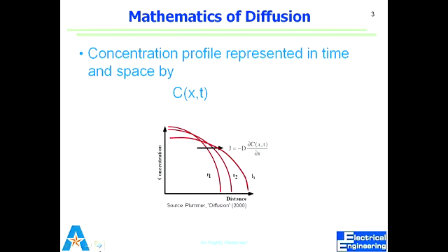And if the impurity concentration is limited, what we see is the profile of the dopant concentration reduces and deepens into the substrate. So in a 1D situation, if this is my depth, my profile would be something like this, and then this will keep on going like this. If this is the concentration, normally we define it in numbers per centimeter cube. So we keep on heating.